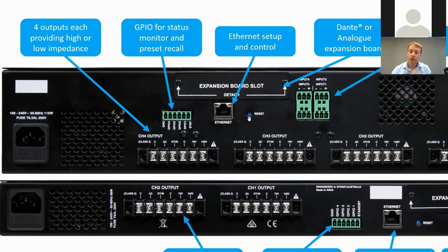We'll speak about this later, but the reset button actually does a few more advanced features, being able to set the product into resetting its IP address, the ability to reset account details, and to obviously completely reset the product. That reset button allows for a lot of flexibility. A typical use case is when you come into an install in a year's time that someone else has done and not documented. You don't have any idea of what the IP address of the amplifier is. We'll go through how that reset button can be used in order to access the product if you don't have access previously.